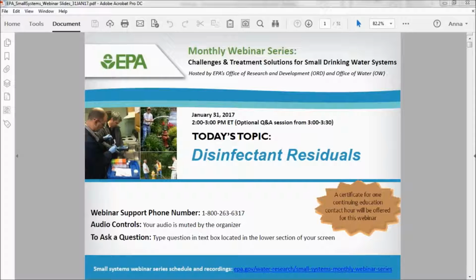Okay, super. Here's another question for you. This person has seen quite a bit of data showing a total coliform or E. coli positive hit along with high chlorine residual in that sample, sometimes over 1 milligram per liter. How would you account for that?